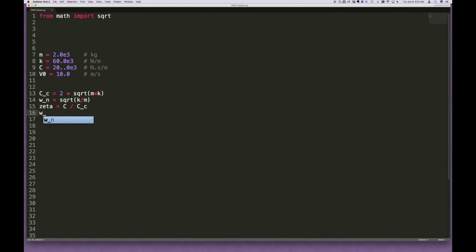The damped frequency, omega sub d, is equal to the natural frequency, omega sub n, times the square root of 1 minus zeta squared. To do a squared in Python, it's like that. It's 2 asterisks. All right, and Tmax, we showed this previously in this problem, is equal to pi divided by 2 times omega d. And we should import pi as well. That's part of the math library.